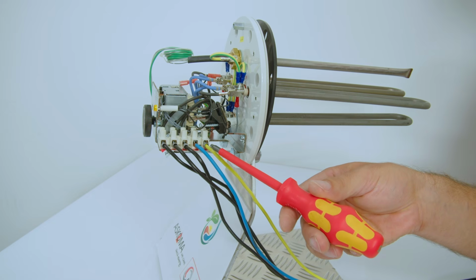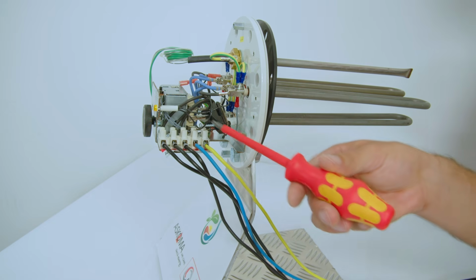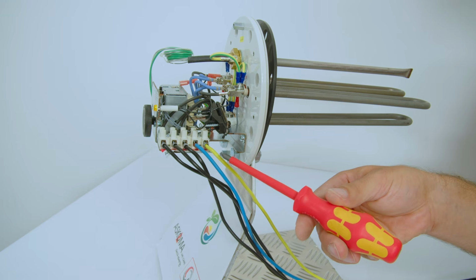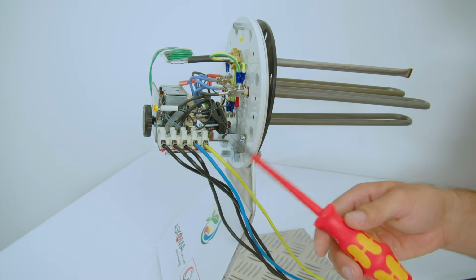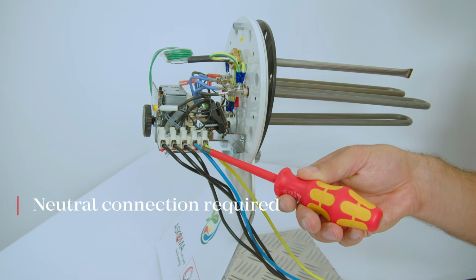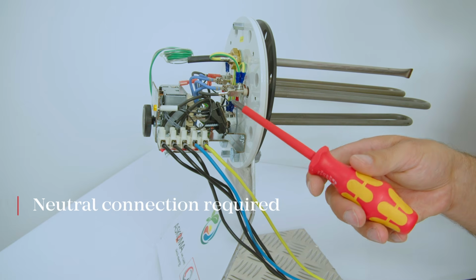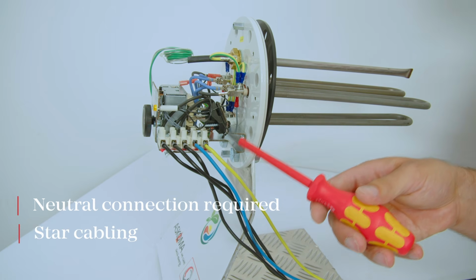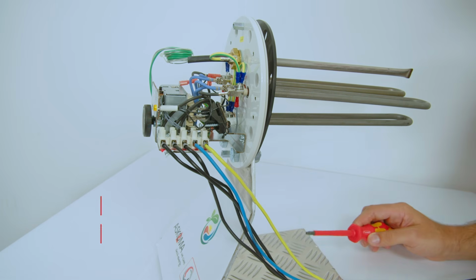With other heating rods, it might not be as well indicated as it is here the case. If you have any doubts, then check the manual. As mentioned in the beginning, we need the neutral conductor connection and also make sure that the cabling is done in the right way. We need a star cabling and not a delta cabling.